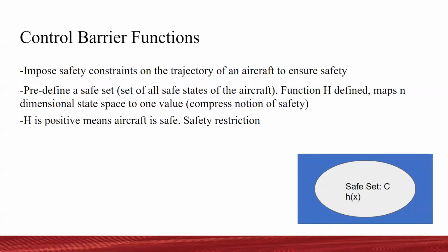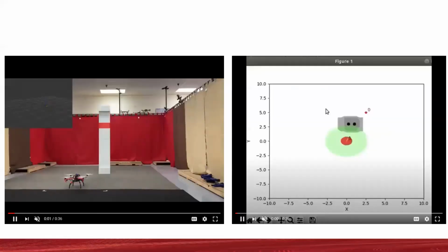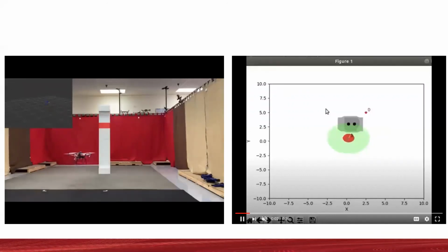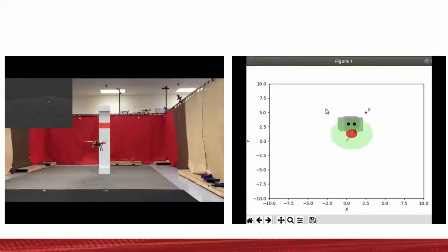So the method that I took was to use an existing repository that my mentor created and try to validate it on a drone platform to see if the results matched. This is shown in the video that's playing right now. My approach was to create a drone with a Raspberry Pi 4, an Intel T265 to localize indoors, and a Pixhawk autopilot in order to receive position information.